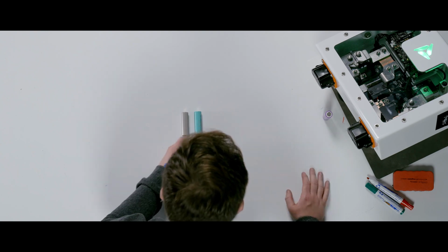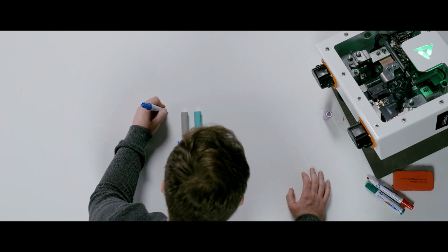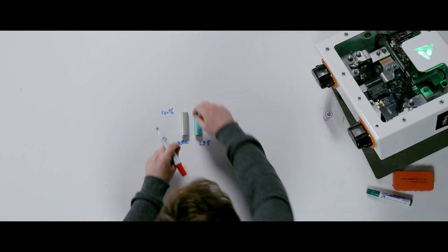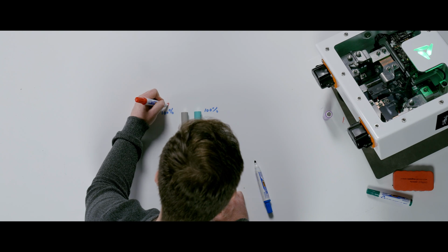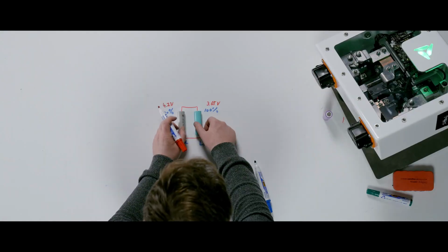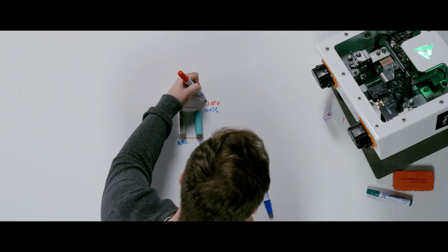So in general, you can't mix different battery cells, different chemistries, because they have to have the same voltage between the two. So if this was an LFP and this was an NMC, and if we say that they're both at 100% state of charge, if you get a multimeter and measure these, this one's going to read 4.2 volts, this one's going to read 3.65 volts. That's very important, because if you were to then connect these together with a wire on the same bus, what would end up happening here is this one, because it's at a higher voltage than this, would flow current into the other one.